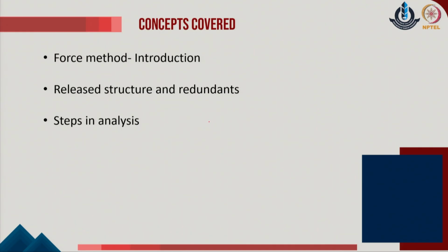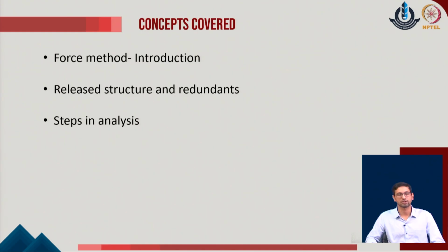We will try to introduce the standard force method, consider the standard cases of the released structure and the redundants in the given system, and then we will try to see what the basic steps in the analysis are. While doing so, we will see that the given content can also be represented in the form of a simple flexibility of the given system.